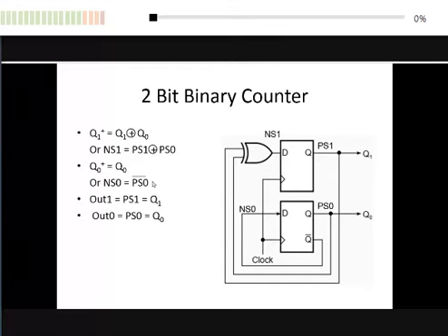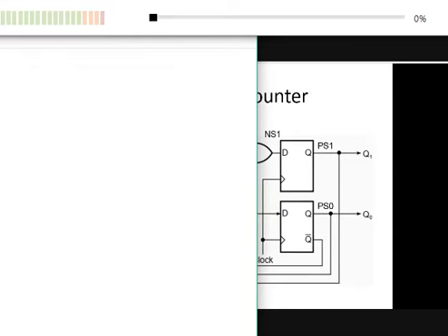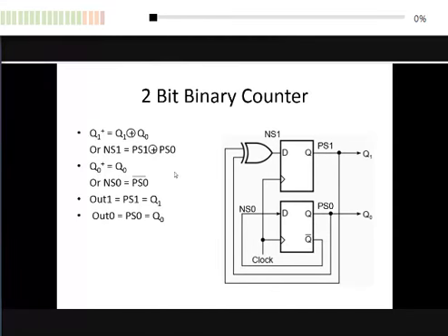Build the K-map. So that's your own exercise, okay? Make sure from this state table, draw the K-map. Can you get these two equations or not? And your output is based on present state only. So then, based on these two equations, build the circuit. It's your own exercise. Just draw on paper. Actually, it's faster.